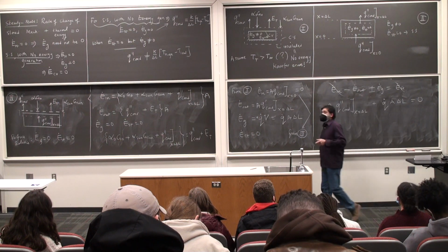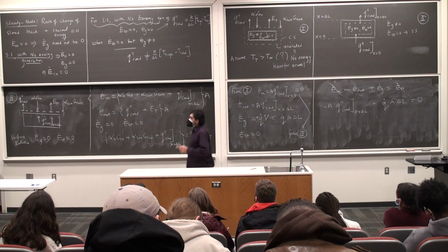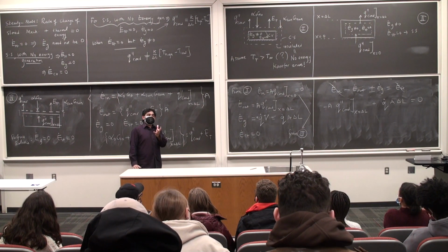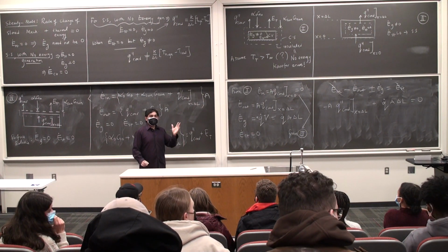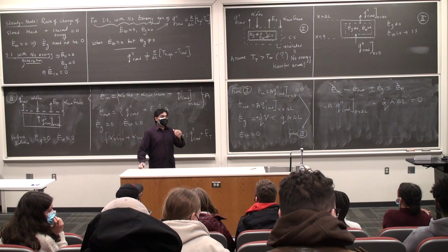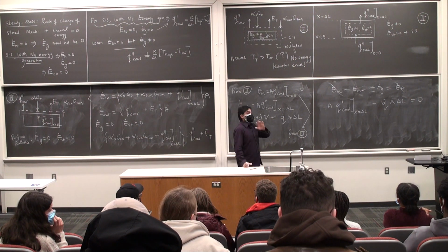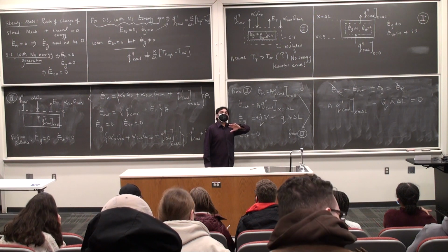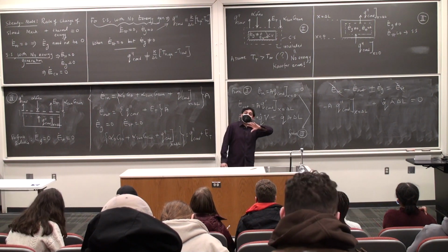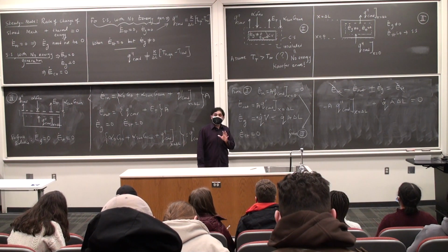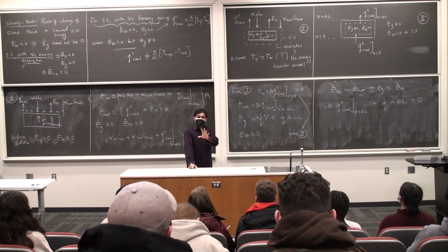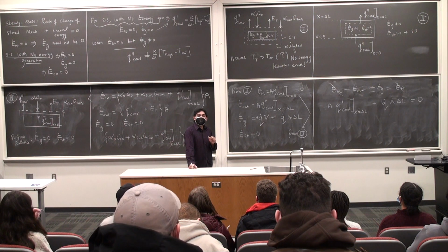And so it should be obvious from these equations that if there is E dot G, any questions? No questions. Sorry. No problem. So it should be obvious that if you have energy generation within a control volume, or if you are looking at an unsteady situation, unsteady heat conduction is something we'll be looking at as well, which means that the rate of change of the stored energy is no longer 0.